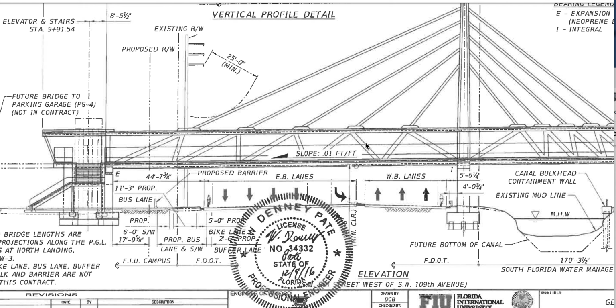And then we have these post-tensioning truss members, which Denny Pate now claims is a redundant system. But they're all supposed to be in compression as per the interview, as you heard Linda Fig and them say. It's all a compressive system. So if it's all compressive, then it needs this to work too. It's not acting as a truss system, where you push down on one, it pushes up on another, pushes down. And this can't act as that either, because this can't go in tension.